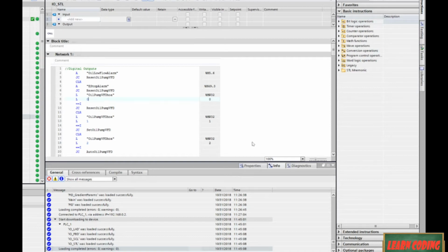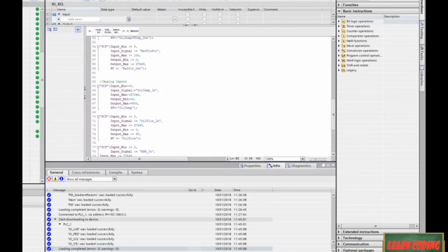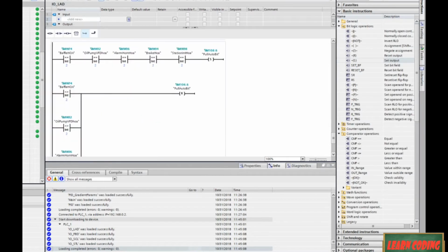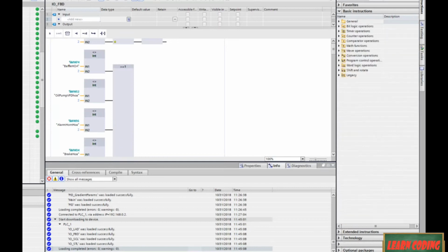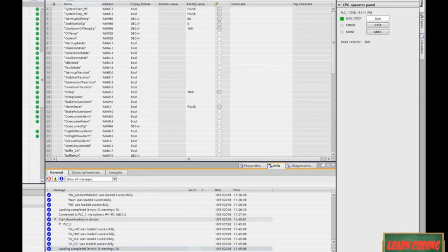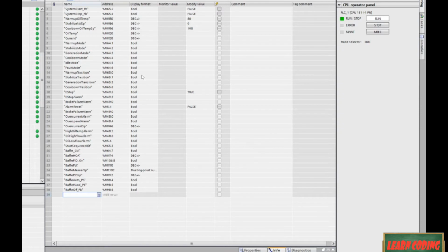Here we go. We're in, we're up, we're running, everything's green, which means we're all synced up. So let's go ahead and close some of these files down, one for housekeeping, two to manage resources and try to stave off TIA Portal's memory leaks, and three just to build a little anticipation while I make you wait. Okay, let's go online with our watch table and see where we're at.